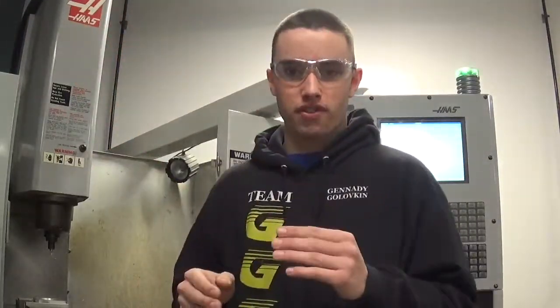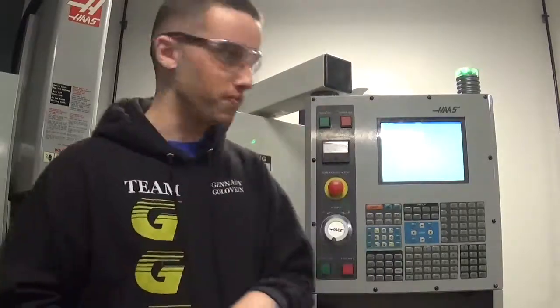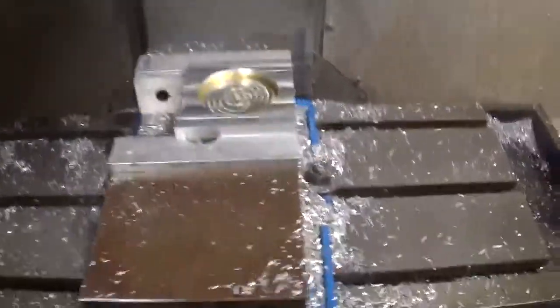And I want to make sure that I successfully set up my work offset. I want to make sure I made my X0 and my Y0 where I want them to be so they work properly with my program. So something cool to do with MDI is you can check that very quickly with like 2 blocks of code. So I'll show you how that's done.